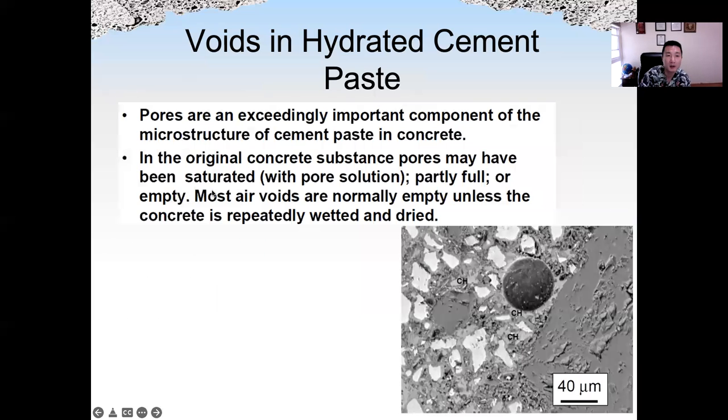So the pores in concrete are very important because they affect both the strength and the durability of concrete. At the beginning, the voids may be saturated because we have enough water in them. We call the water in the concrete pore solution because it is not pure water.